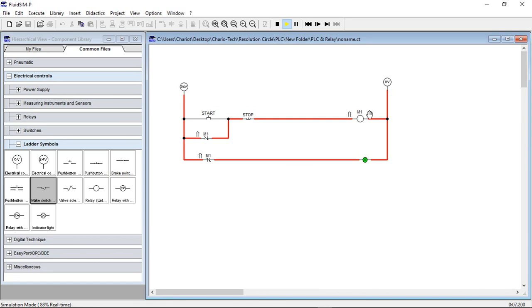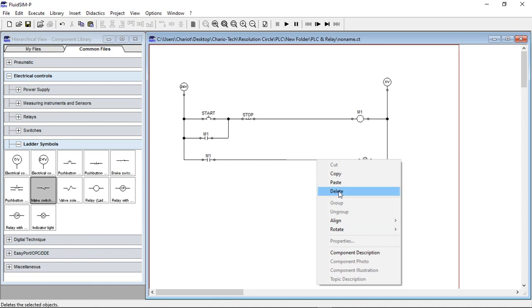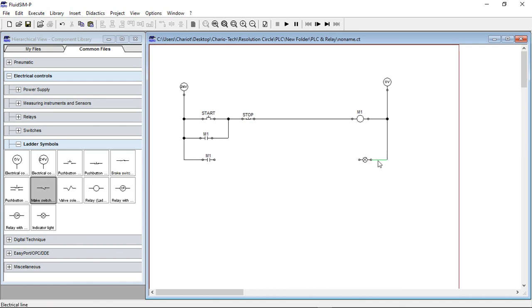then power goes to M1 and my LED is green. When I press stop to delete everything, then my green is off. Okay, let's say now I want my green light to be on 5 seconds after I pressed my start button. Like I'll press my start button once and it delays for 5 seconds before my green light is on.